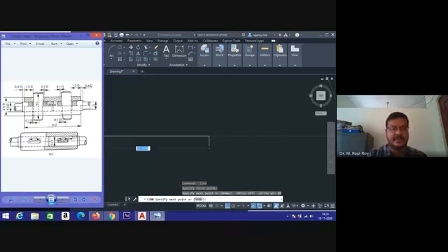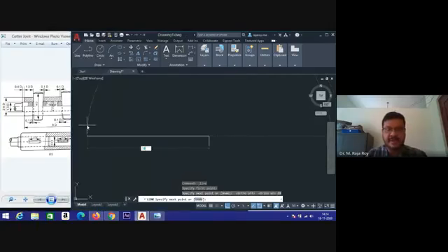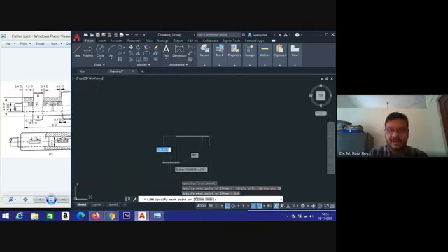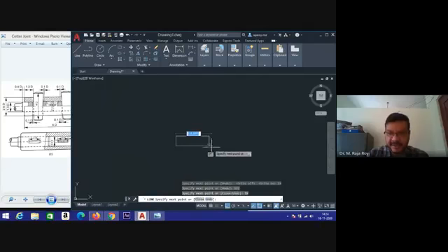You can calculate here 4 into 30, plus, in brackets, 0.4 into 30. The total you get is 132. Now type the value 132 and press enter. Now you are getting a 132 length there. Now downwards again 39. Then you can directly click this endpoint using the mouse, or you can type 132 again. That is your choice.